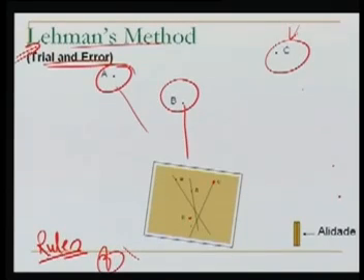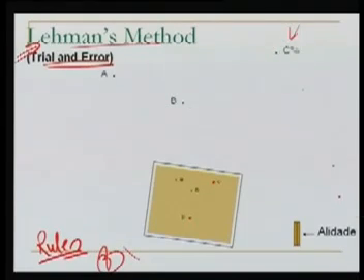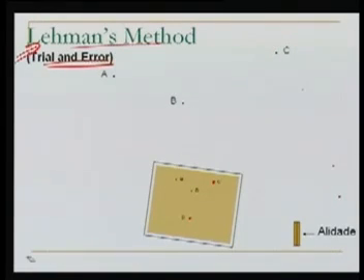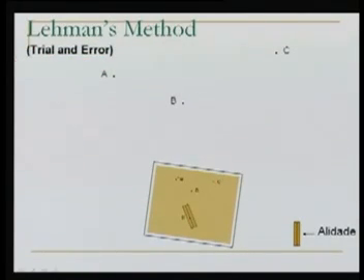What we do next? We keep our alidade along this small p and let's say A. We keep it like this. Now if I keep it like this, will it bisect A? Right now it will not bisect A, because this is a different point.